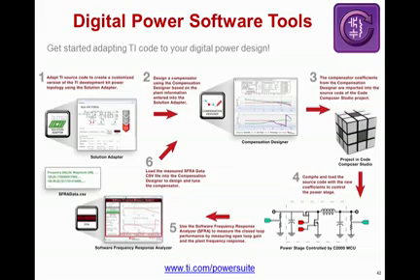This is then plotted, and the values from the SFRA for the plant can be fed back into the Compensation Designer to be used as the true plant measured values versus the modeled values that were originally used. And you can then recalculate and replace the poles and zeros as necessary to tune your digital power compensator.